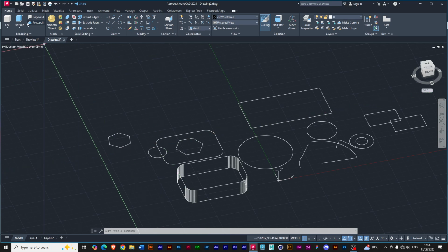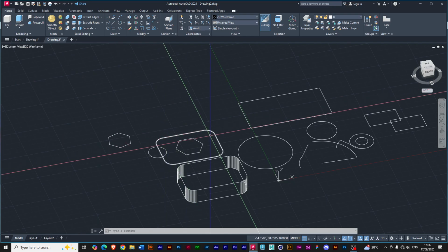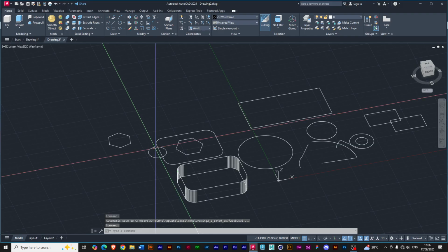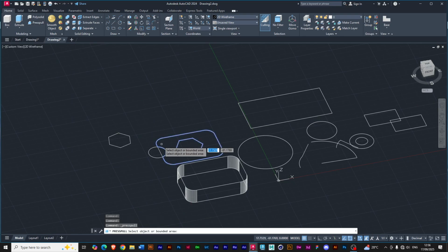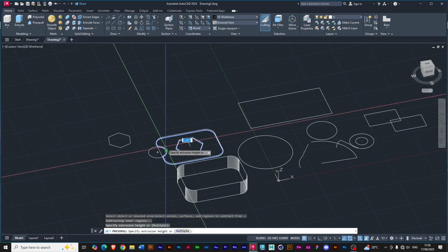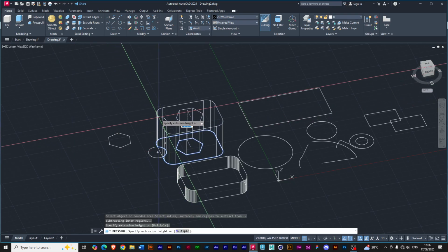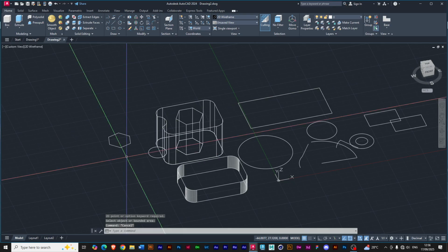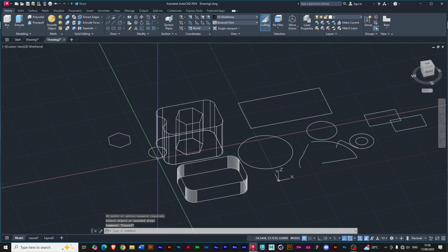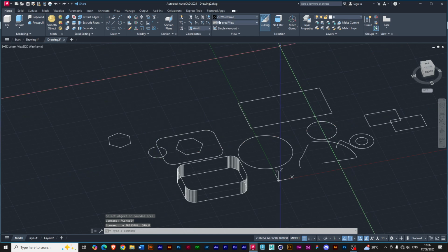If I use extrude, it's going to pick up the whole rectangle. But if I use press pull, it's going to pick up a section where there's an intersection in the rectangle, right? So if I do press pull now, I can pick this section and press pull just that section. Okay. Escape, Control Z.